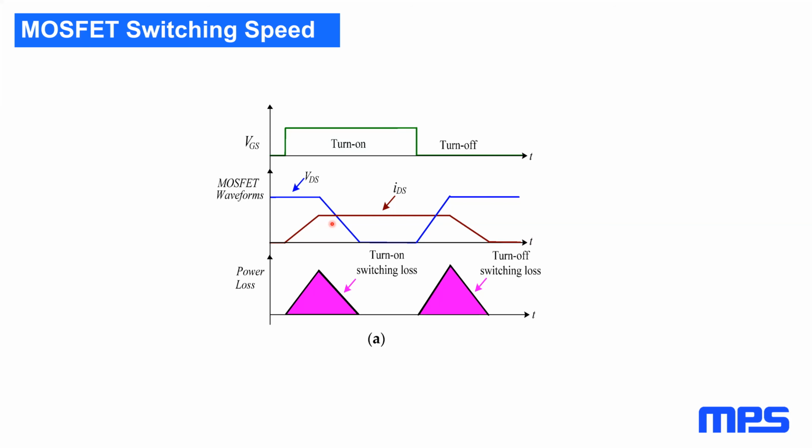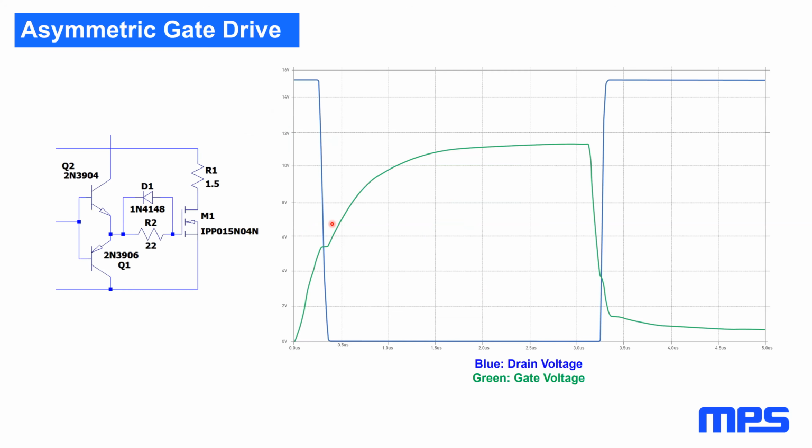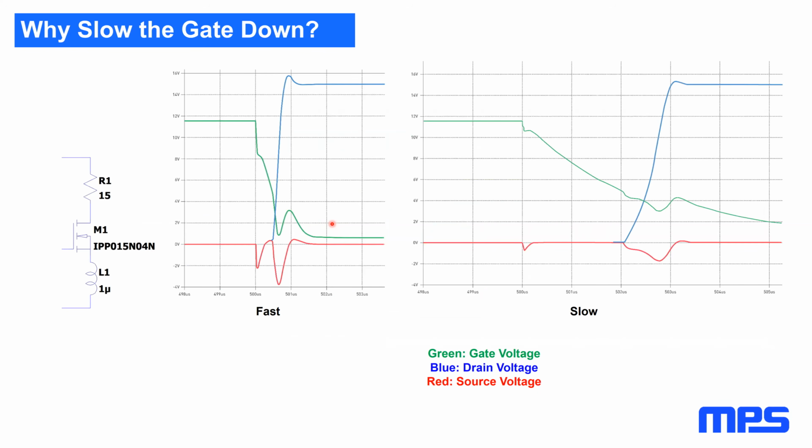Okay, just when we thought we were getting to the end, Pete, there's more coming in. I see one via chat about the waveforms associated with false turn on showing negative voltage on the gate. What was the reference voltage used to measure the gate voltage and the source voltage? Is the spike on the gate voltage, the green one, because of the negative spike on the source one, red, if source is used as the reference for the gate voltage?